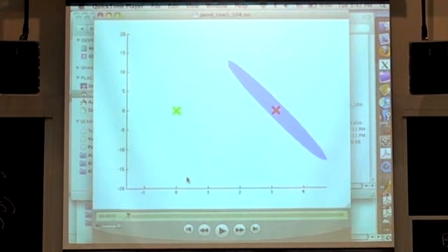Okay? The only difference is every time we grow out in random directions, I'm going to stabilize that trajectory with an LTV feedback and compute the basin of attraction on it. So here we go. Pick a point at random. And actually, I don't always play the RRT trick. I could do lots of RRTs to try to get back to that point, but I'm actually going to just use this as my goal and do Dircol to design a trajectory to get me there. If that works, that's perfectly fine.